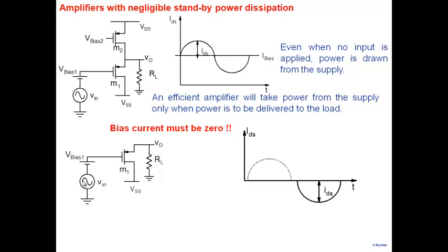Once it turns on, it starts following it. And of course, it will turn off before my negative cycle is actually finished. So it will turn off here. So if I look at this particular stage, my positive cycle is missing. My negative cycle doesn't conduct for a while, and then, till about Vt or so, it starts conducting. And then before Vt is reached here, it again switches off. Obviously, it's not a good amplifier.